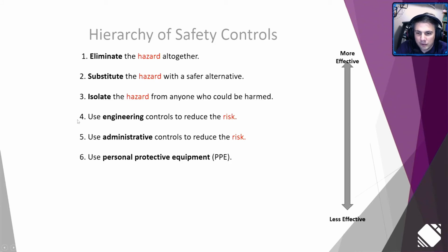It's inherent in the design that the power is going to be disconnected before anybody is injured, and when that power is disconnected, anybody working in the area identifies that that's a problem and needs to mitigate that issue before returning power. Next one would be administrative controls. An administrative control would be a procedure: do not open this cabinet until the power is disconnected upstream.